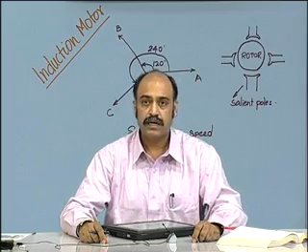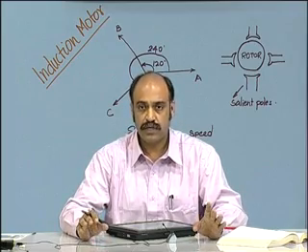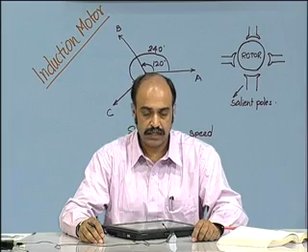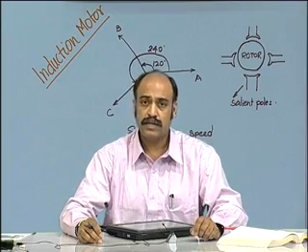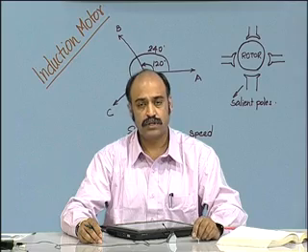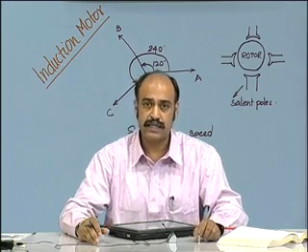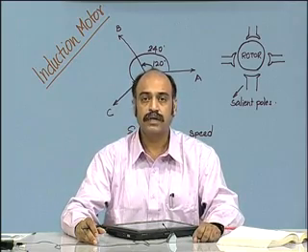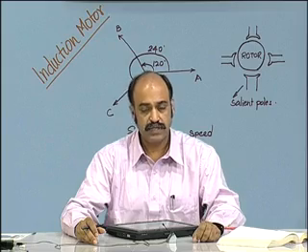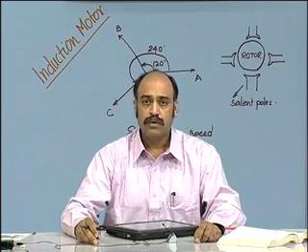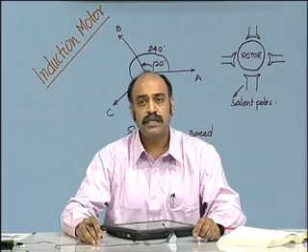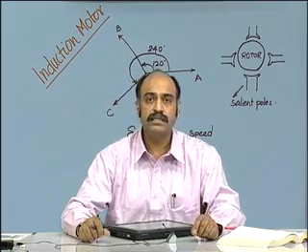So the synchronous frequency is fixed if the number of poles is fixed in the case of the induction motor. If the synchronous frequency is fixed, then the shaft of the induction motor is going to be less than the synchronous frequency only by the amount of slip. So more or less the induction motor is a reasonably constant speed motor.